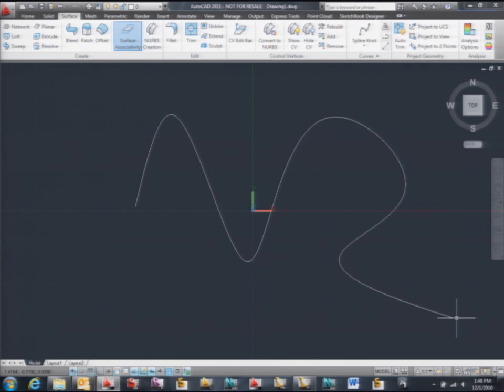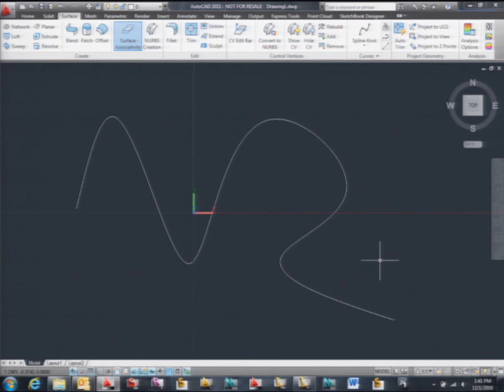But removing 2 clicks in our 14, 15-hour-a-day schedule with the application is a lot. If you start removing 2 clicks or 3 clicks here and 2 clicks or 3 clicks there, you probably have 1 more hour to keep working, but on more meaningful stuff. So that seems minor, but it's not that minor. So I was saying that we had the option to create the spline through fit points. Fit points is one of the ways to define a spline. The fit points, again, are points through which the spline is going to go.